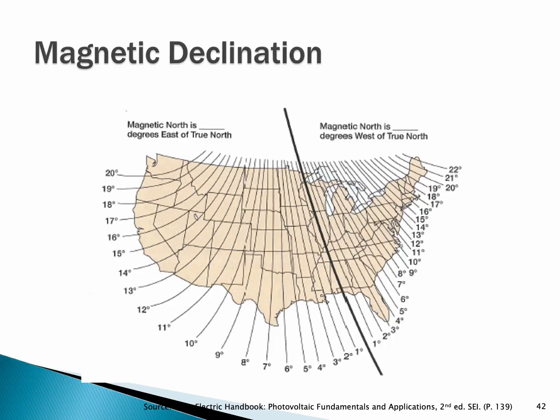I talked briefly about a thing called magnetic declination. Not something that we have to really think about too much here in Illinois or Wisconsin, because the zero line for our compass goes roughly down through the Mississippi area from Minnesota down to the southern tip of Illinois, and then wanders off to the east. But nonetheless, we're about 2 degrees off from true north-south.